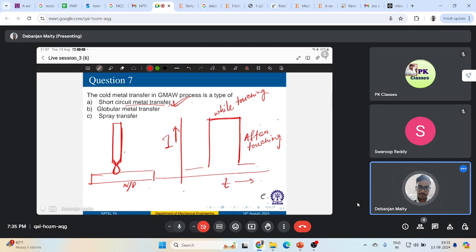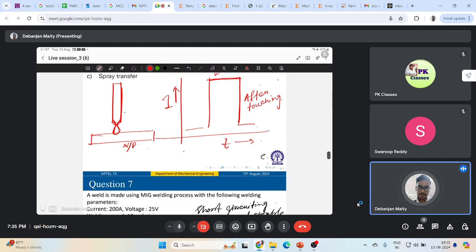So this is how you will control your feed rate or the wire feed rate in such a way that you can help in managing the heat input, which will be crucial for welding some metals. So basically the ultimate result is low heat input, minimized heat distortion.